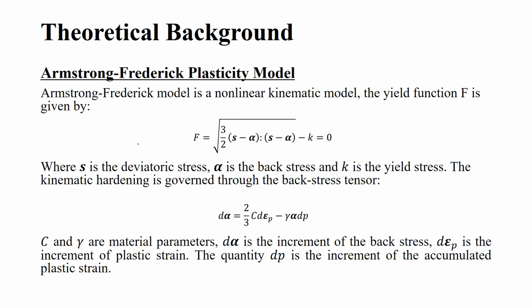There are two types of cyclic plasticity models: the constitutive and the phenomenological models. The constitutive models are based on solid mechanics approach. On the other hand, the phenomenological models are mainly based on the experiments. For magnesium alloys, the constitutive plasticity models have strong limitations. In general, constitutive plasticity models have three main parts to follow the material response under plastic deformations: the yield function, the flow rule, and the hardening rule.